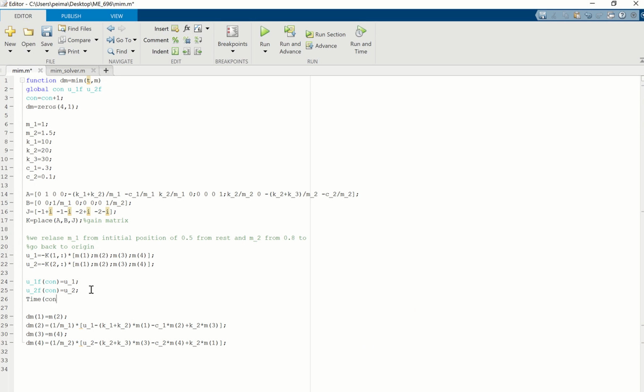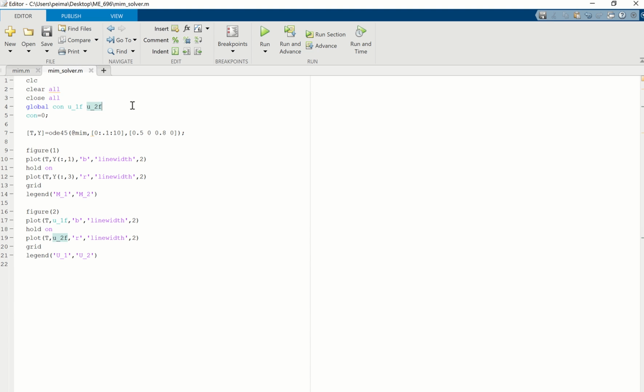time of control, because the time step that you are saying and the amount of vector you are saying are the same. You're going to say now, put the time that is exactly counting here. This is the time, that's right, T. And now make this again as time. Why doesn't this shift work? Shift, time, that's right, global. Please do it at home to make sure that you roll with me. Okay. Now if instead of the total time from ODE you say time, these are tricks in MATLAB, huh?